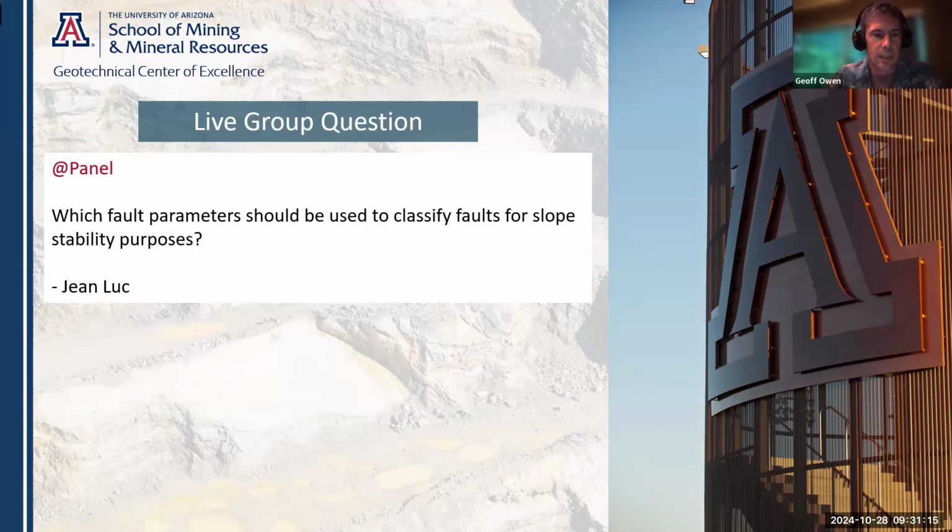And then also evaluating the importance of that structure for your fit for purpose model. So if it is going to be for geotechnical purposes, what is the location of this and the orientation of it relative to a bench or a slope as well? So I think that's the nitty gritty for some of the details of collecting in the pit. Those could be some of the options I'd look at for parameters.